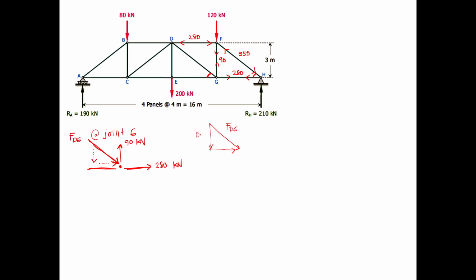Let's say this one is DG vertical, then DG horizontal, and this one is angle theta. So DG vertical is equal to FDG sine 36.87. That's just my way, since I already know the resulting value, but if you want to make it step by step, or if you want to make your answer sure, you can write each step to be sure.